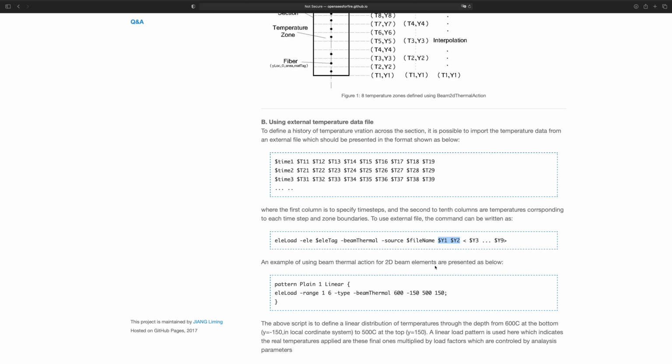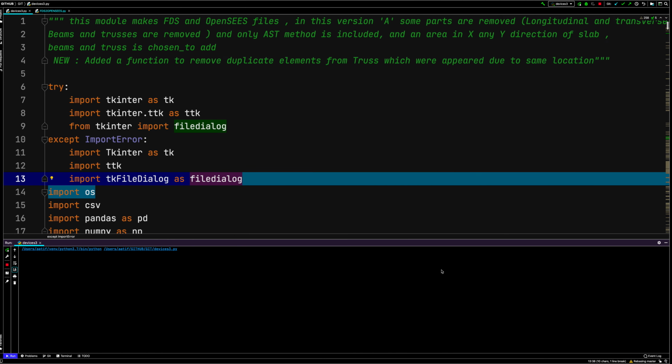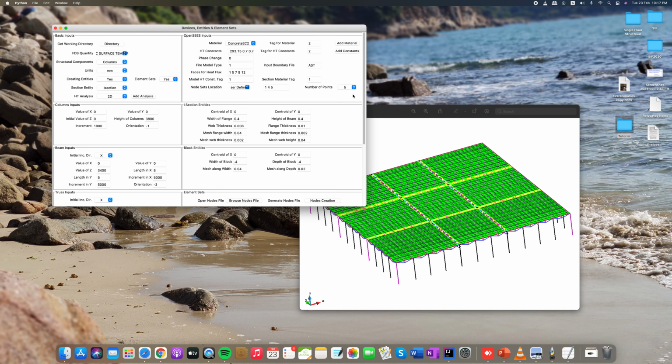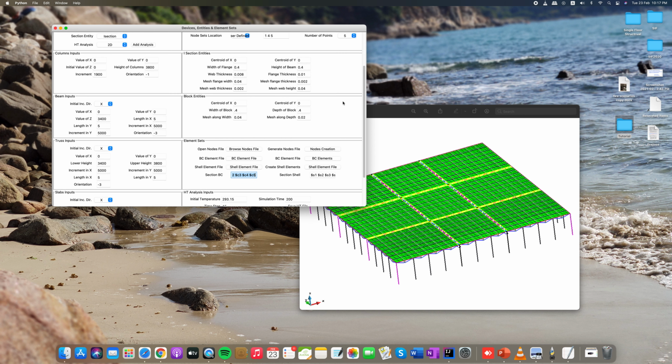This is for structural analysis. It is required because you would be getting 5 different files. If you need data at 5 points, it will show those 5, so you have to provide 5 values here, and the same for shell. For slabs, whatever you are representing by shell elements, you have to go like this.